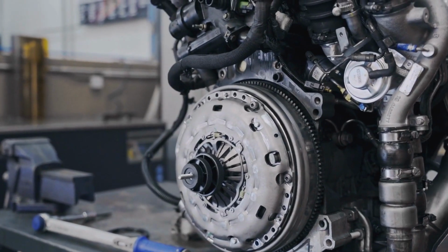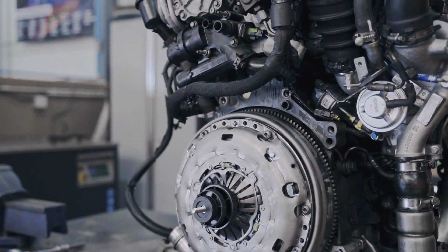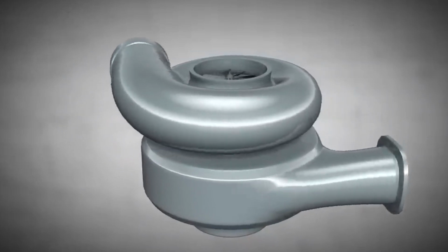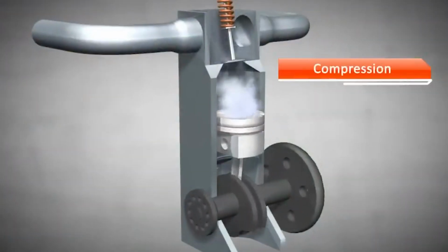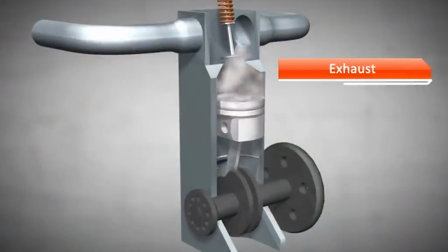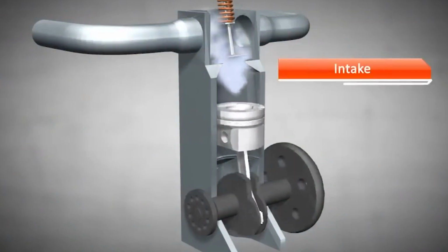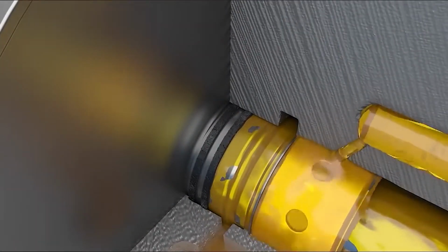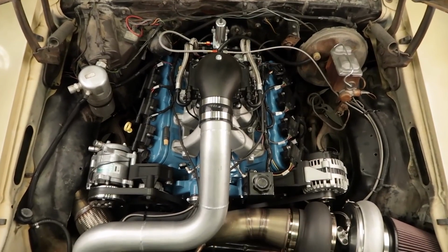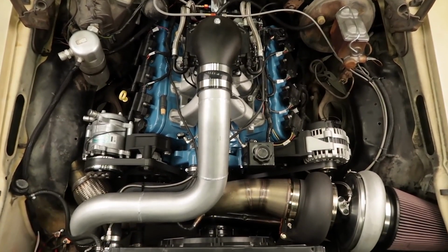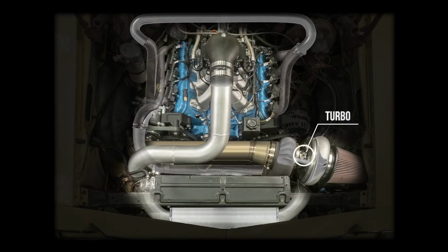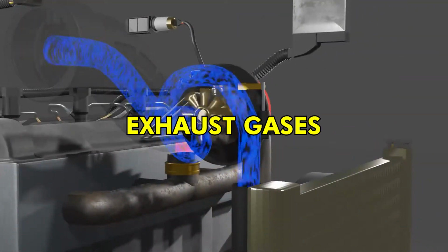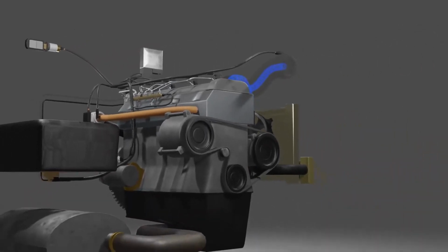On the opposite end, the compressor wheel or impeller is enclosed in the compressor housing, which draws in ambient air and accelerates it before compressing it. The compressor housing's volute and diffuser sections convert the high-velocity air from the compressor wheel into pressurized air that feeds into the engine. The turbine and compressor are directly linked by a high-strength shaft, which allows energy transfer. The turbine extracts power from exhaust gases and transfers it mechanically to drive the compressor. This integrated design enables effective energy recovery from exhaust gases, boosting intake air pressure and ultimately engine output.